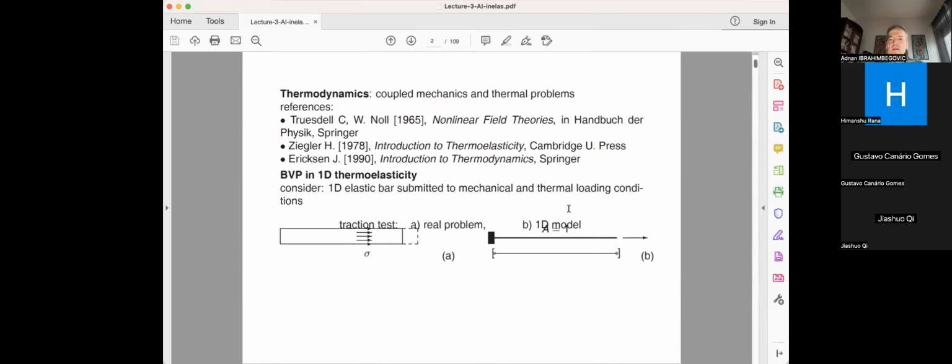If you go to thermo-inelasticity, besides these curvilinear coordinates that made reading quite difficult, they also advocated material's historical long memory, which is if you want to get stress at time t, you have to integrate behavior from minus infinity to time t. First of all, who knows what happens at minus infinity? Nobody was there to tell you what it was like at minus infinity. And secondly, it's not really practical because such a long integration is not the way to go. So it turned out that the proper way is really these internal variables, which I described not by integral equation, but by differential equation or evolution equation.